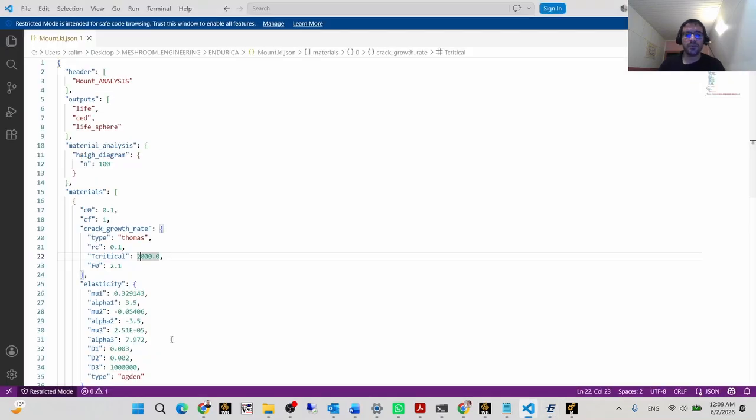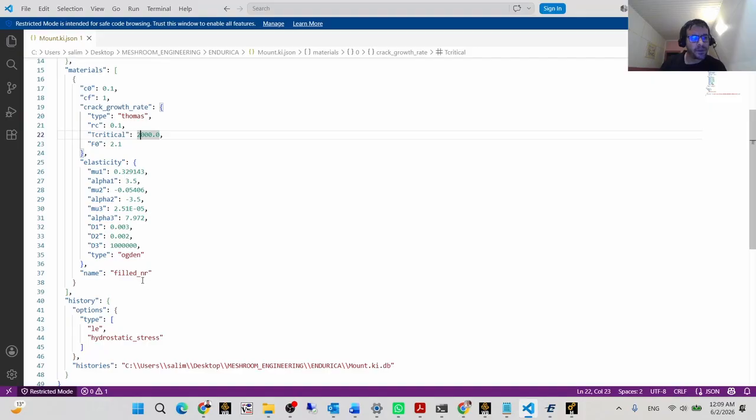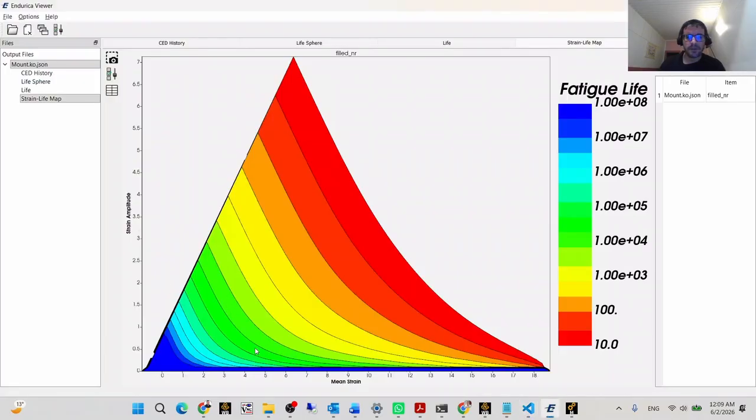So I'm wondering if it's an area. Natural rubber, I'd expect that this blue side would dominate a bigger space here to show how the strain crystallization is enhancing life by reducing the critical area. But this is the case for this one. So in case you're interested in observing these differences, you can make a comparison between two different rubbers.